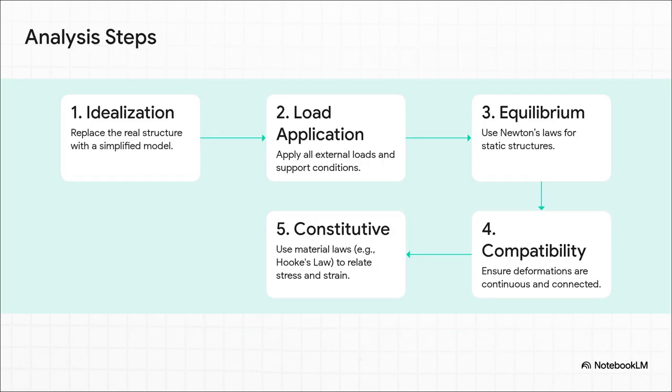See, analysis isn't guesswork. It's a methodical procedure. As you can see here, it has 5 main steps. First, idealization, where you replace the real structure with a simple model. Second, load application, where all the forces are applied. Third and fourth are equilibrium and compatibility, where you use equations to check stability and deformation. And finally, number 5, constitutive, which is where material properties come into play.